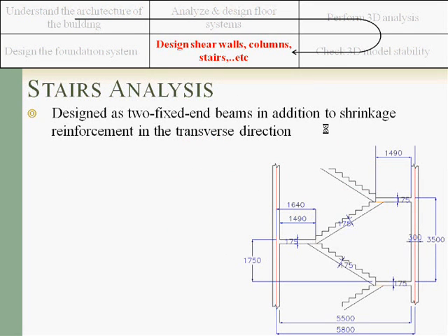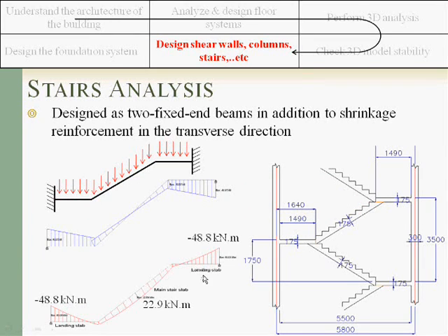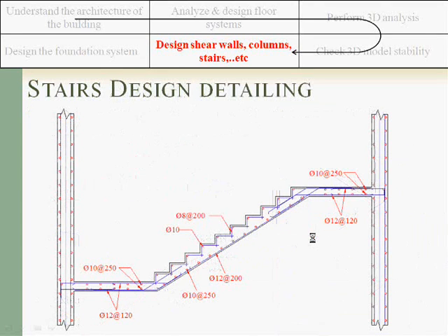The stairs were a very nice structure, which we consider as fixed with the shear walls in order to minimize the moment. We get the negative and positive values using STAAD software, and then we designed this stair as a continuous beam supported on the shear walls. As you can see, this is the negative reinforcement, detailed in a very correct way, because we have to make sure that all these junctions are able to resist this tension.